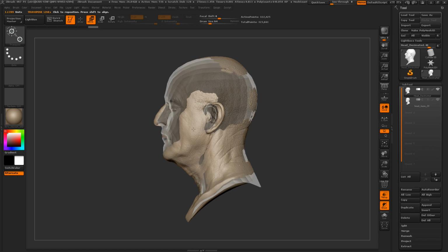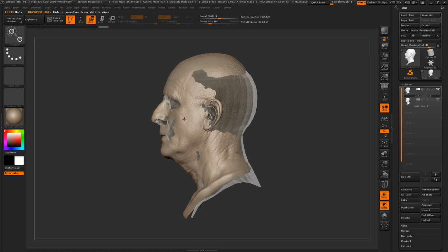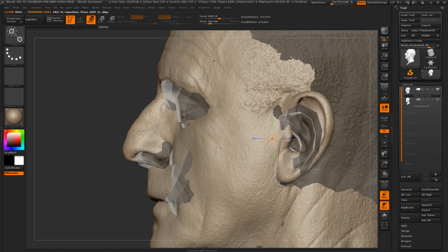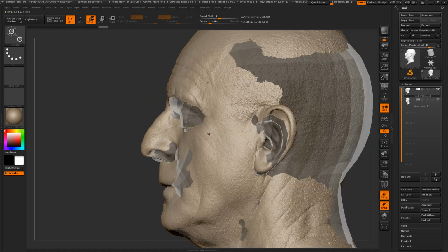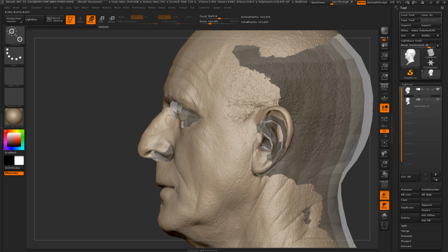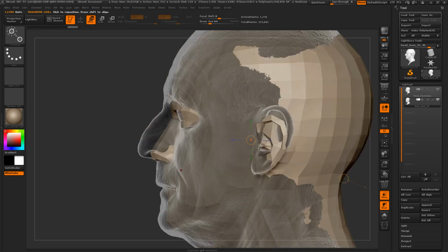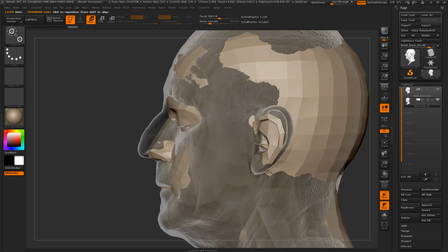So we can just rotate it like so and try to match the general locations of eyes and mouth. The corners of the mouth and the corners of the eyes are the two key areas that you want to align, because everything aside from those areas is very easy to align. Sometimes you'll have to rescale the low poly or the high poly to actually hit the right placement. So I'm going to rescale the low poly, also be a little faster and easier.